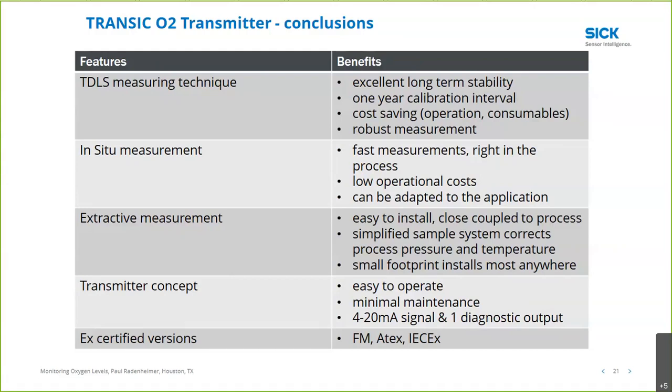So you do have to be careful. Look at the sample point, look at the turnover in the tank. I imagine stratification can be an issue, and we can certainly have one of our installation experts come out and take a look at that and give you some advice at installation time.